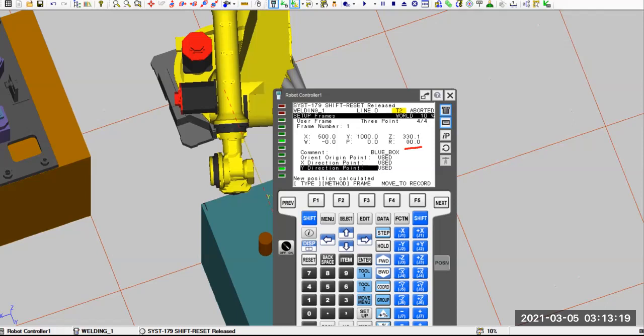The default robot 000, remember, is somewhere around the base. So that's world 000, which is default. And we use corner number 1 as the original point, that's what we record here. Where exactly is this point? If you look at this corner, in relation to this world 0, it's halfway on the square. Remember, one square on the floor is 1000. Sorry, it's only one half, so 500. So that's why you got 500 on the x direction.